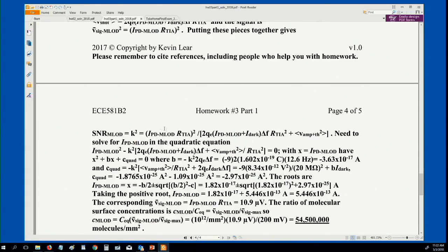So there's a term for the signal magnitude that comes in that's proportional to C squared, or in this case, IPD squared. But down here in the noise for shot noise, this stuff isn't changing, but the shot noise is changing because IPD is changing because the concentration is changing. The average current there is changing. And as a result, shot noise changes.